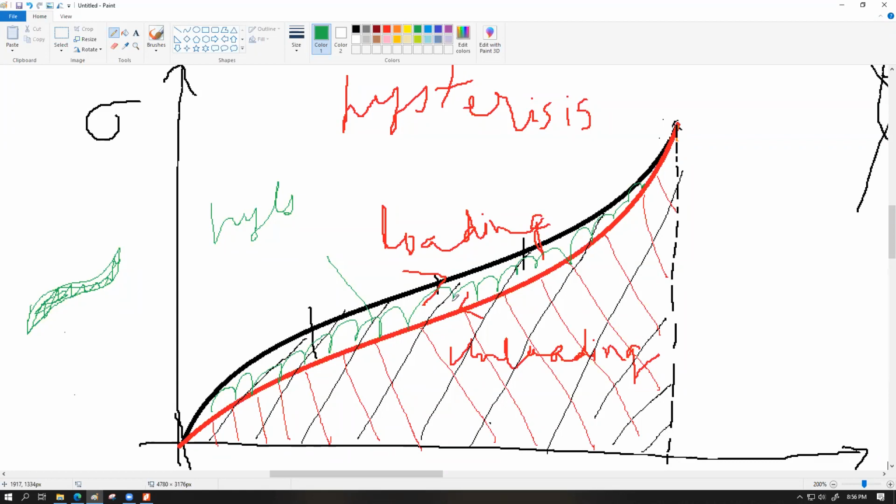Trampoline is usually made from a slightly stretchable nylon string cloth, which is flexible but really highly strainable, and the ends are usually connected with springs, metal springs. বুঝছো কি বলছি? জি স্যার। Ends are usually connected with metal springs. So the trampoline usually stores energy by the elastic deformation of those springs primarily, not by the cloth on which the people jump. But if you want to replace those springs by cylindrical shaped rubber, then we would appreciate this loop to be as thin as possible, so that more energy will be provided back to the jumper. Less energy would be dissipated as heat.